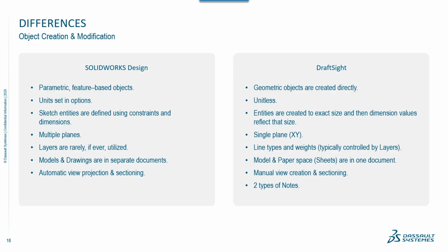As you know, models and drawings in SOLIDWORKS are separate documents. Now, the references are there. SOLIDWORKS maintains those, understands that this drawing is created from this model. DWG files mostly are one file. The entire drawing is in that one file.